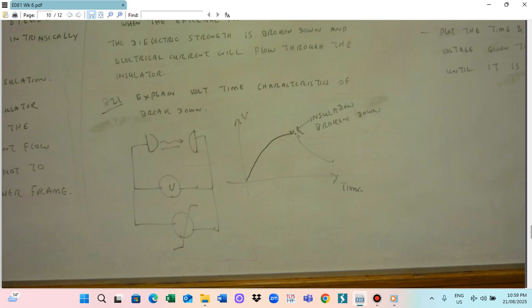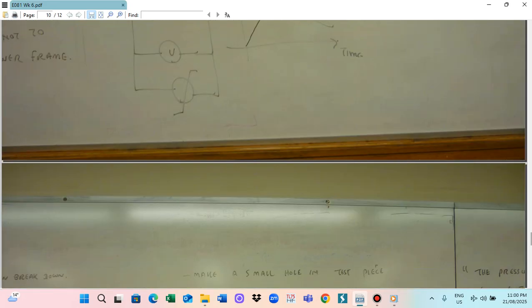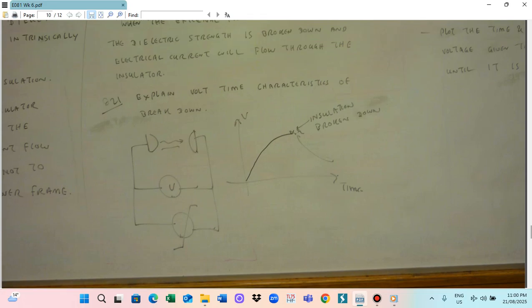To summarize tonight, firstly I talked about viscosity and gas. Gas can be a perfect gas or a real gas. We also talked about gas viscosity, the Reynolds number, Avogadro's law and Charles's law. Those are the properties of the gas. Together with this, I also talked about dielectric strength, the ability to withstand electrical current, and that it can break down when the voltage is too high. We also talked about transmission lines, insulation properties, the insulation breakdown procedure, and the time characteristic of the breakdown.